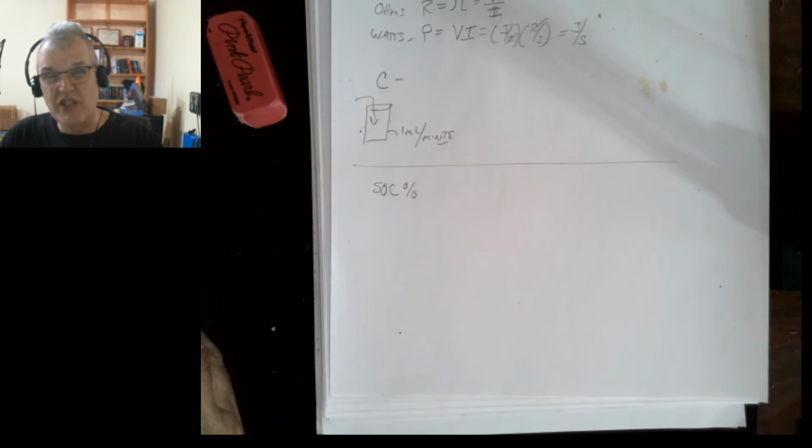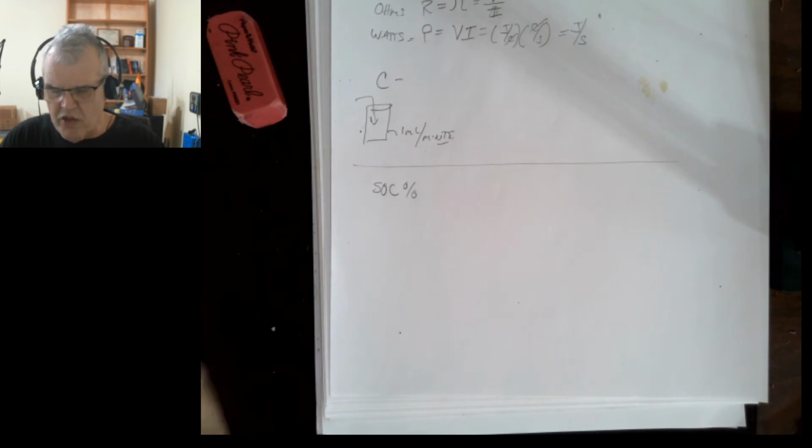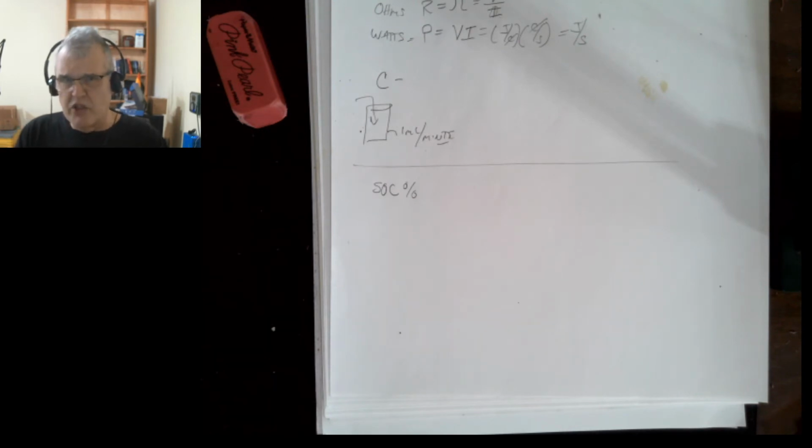What is the percentage that you have discharged of its capacity? So depth of discharge of 80% would be a state of charge of 20%. Okay, so that kind of gives you the discharge capacity. And their terminal voltage. These are some things that are important to know. Terminal voltage is what voltage you measure at the terminals of the batteries.